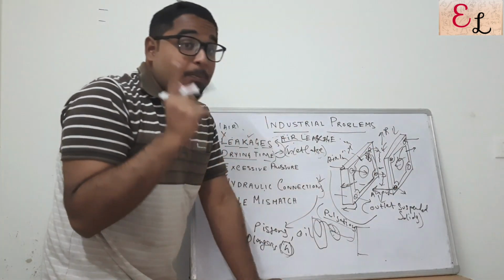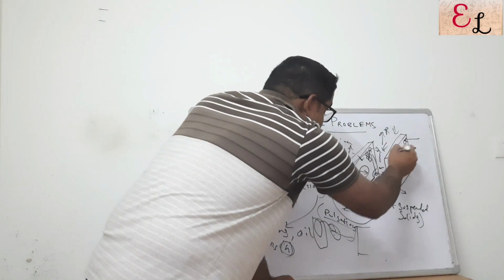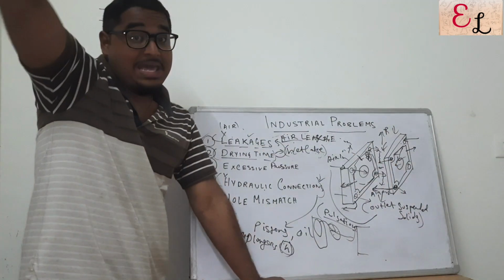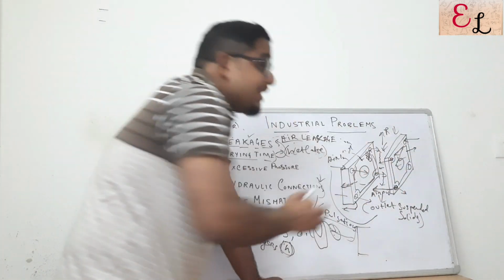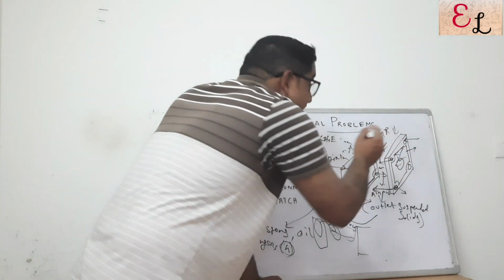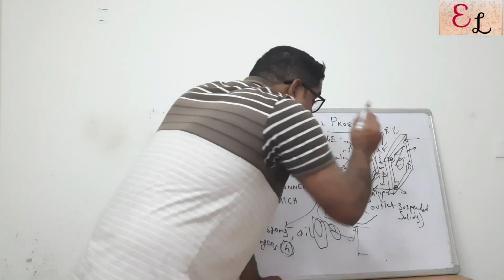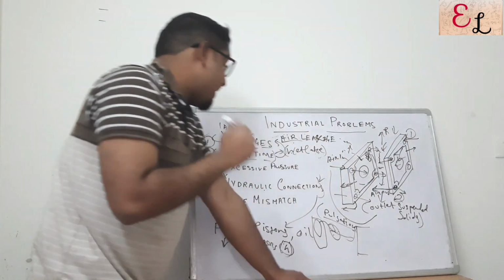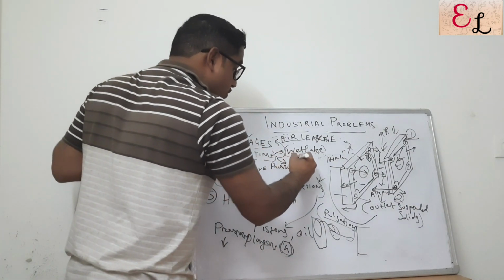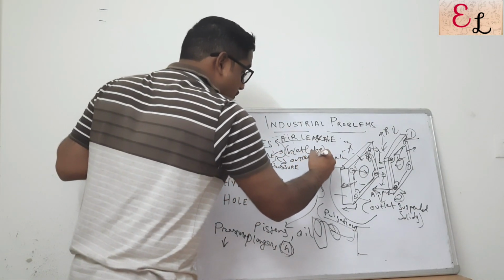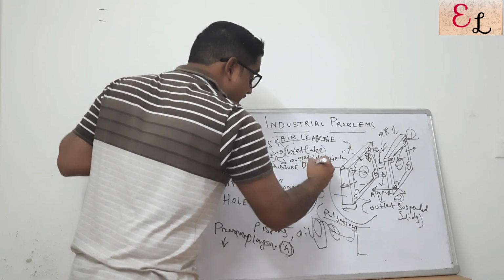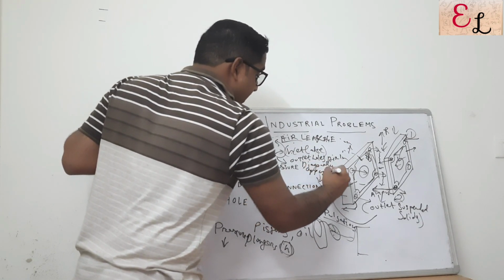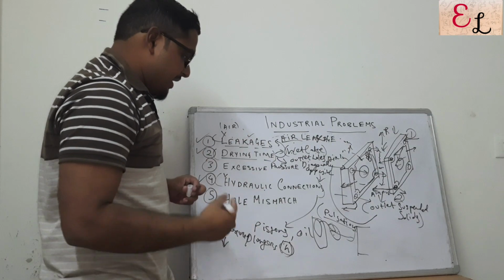So what happens is the air primarily finds the less resistance path in this hole and tries to pass out through this. Whereas it was meant to cover the entire cake and circulate through the entire cake and hence dry the entire cake, that doesn't occur because we give a lesser resistance path to the air through this hole. So if one hole is opened here, the other hole should be opened here for air drying. Very important is which outlet holes you open. You should always open diagonally opposite outlet holes for air entry and exit. If air is entering here, it should exit here.